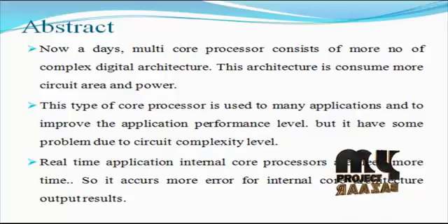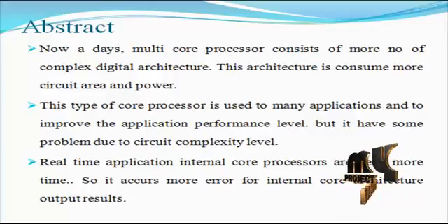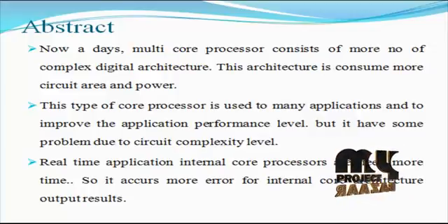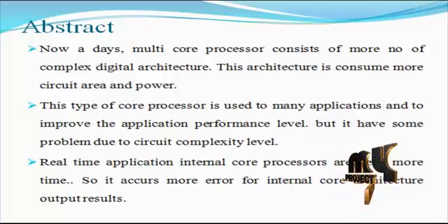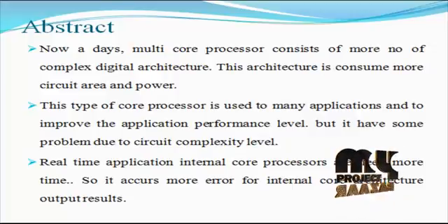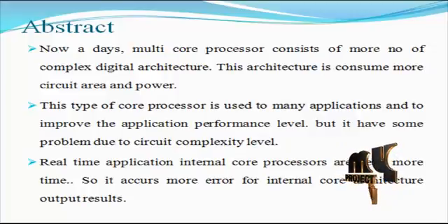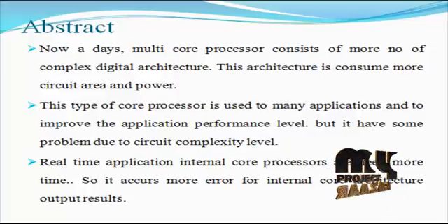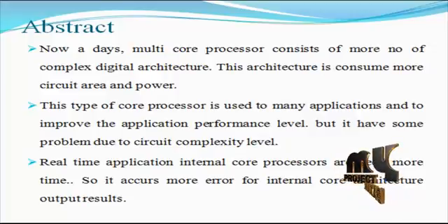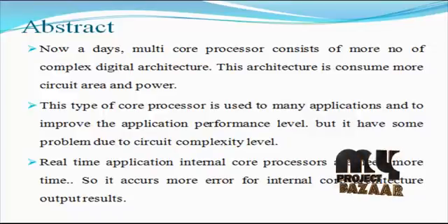Instead of the typical test response data from the cores, the test output data used in this paper are majority values. Thus, the test responses from all the cores can be tested in parallel. In both test modes, the proposed TAM can be implemented with an on-chip comparator. The proposed TAM can test multiple cores, as shown in the proposed TAM architecture.